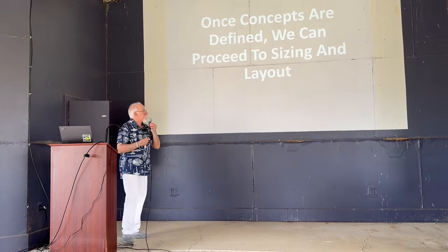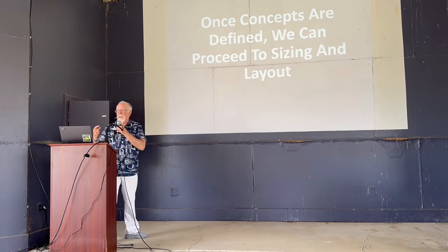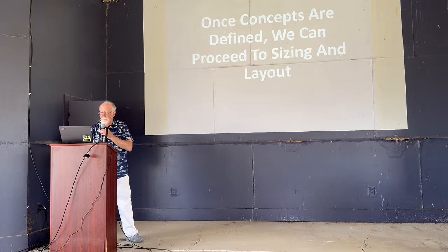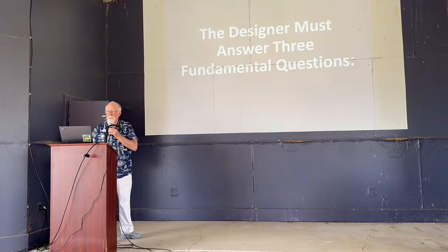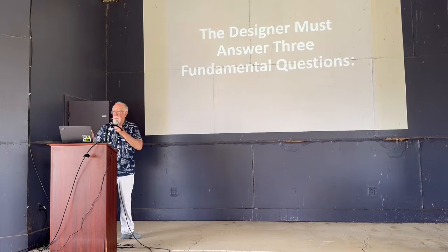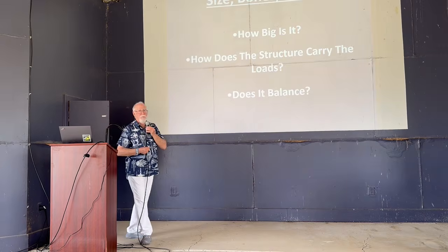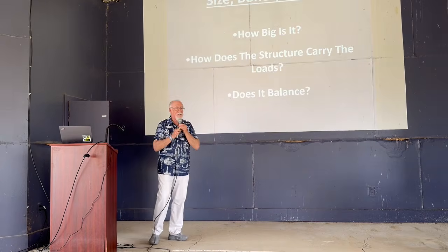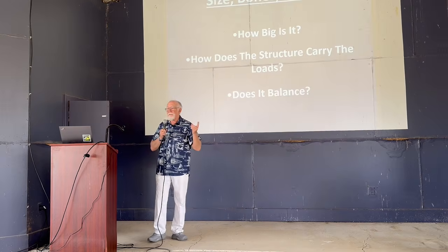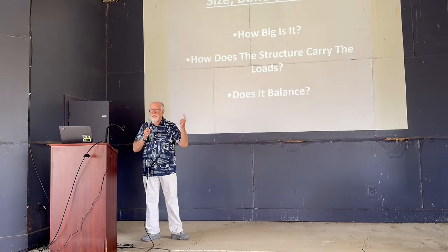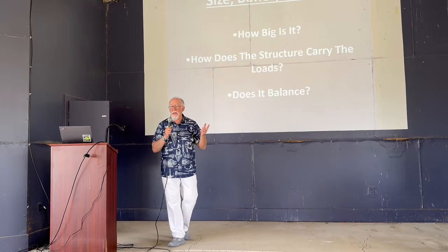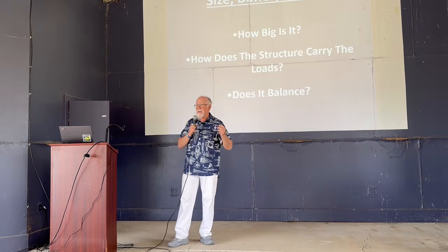Okay, so we've got our concepts. Now we're going to get into sizing and layout. Now we're going to get into the guts of it. So, once again, 3 basic questions. Size, bones, and balance. This is the mantra I teach my students. How big is it? How much engine does it need? How big is the wing? Fuselage size, all that. Basic sizing.